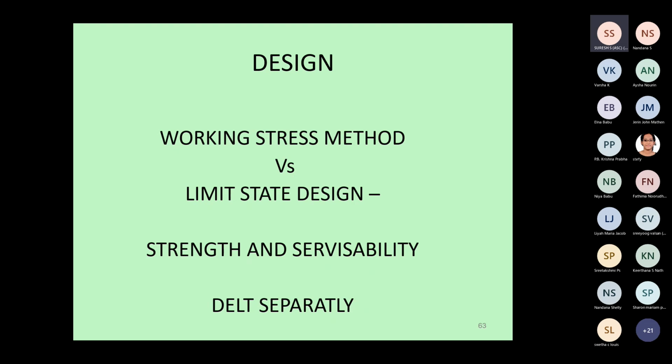So the crack should be controlled, deflection should be controlled, corrosion should be controlled if it is excessively corroded. So all these parameters are serviceability parameters. They are called serviceability limit states, in other words. So we should match strength limit state and serviceability limit state. And the load factor that is applied on the loads for each of these is different and hence dealt with separately.